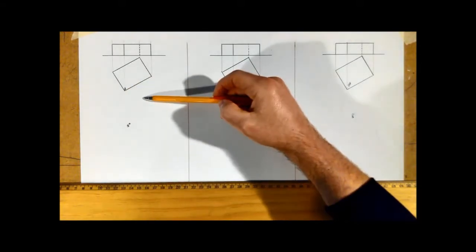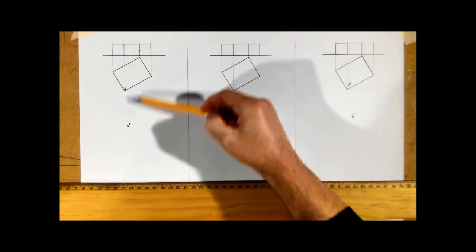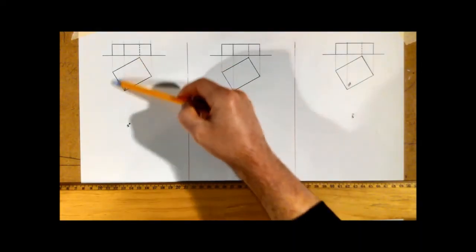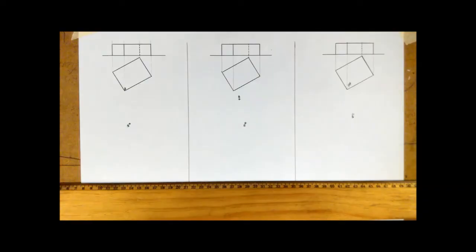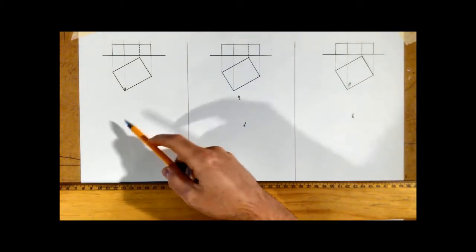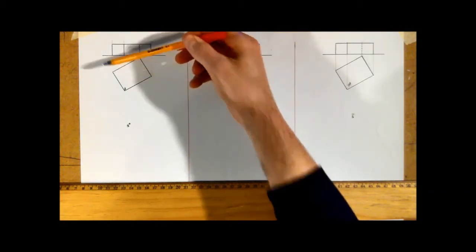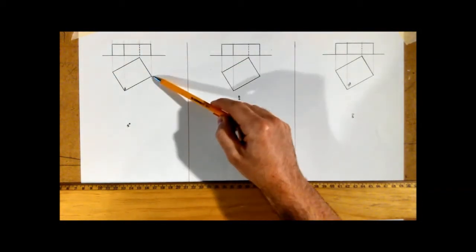Okay, starting with the one on the left, we can see we have a spectator in this position, and we have the box in this position a certain distance away. Now, what we have to do first of all is set up our picture plane. The picture plane is where the person would see the image of that box. If you imagine the spectator standing here, what they will see is as far left of the box in this position and as far right of the box in this position.